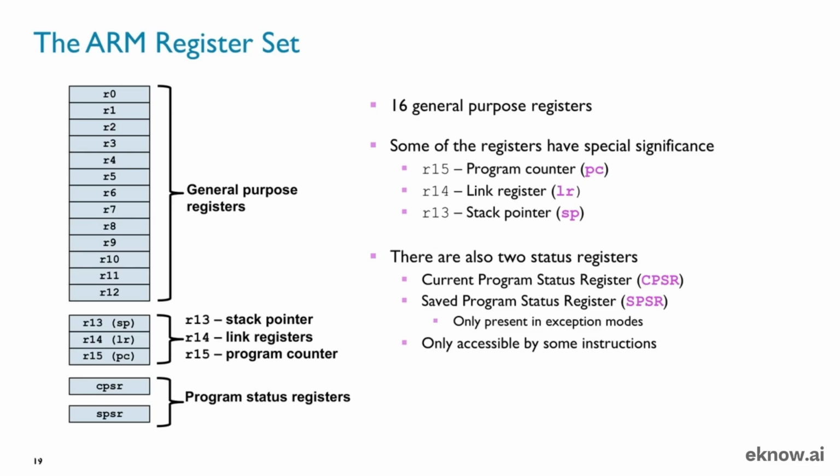However, as you can see, they aren't all used for the same things. Let's first look at the main group, from R0 to R12. These are the true general-purpose registers. You can use them for almost any data manipulation. When you're adding numbers, storing temporary values, or moving data around, you'll primarily be using these registers. They are your main workhorses.